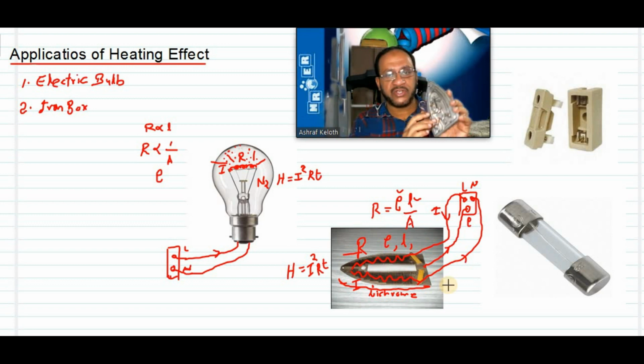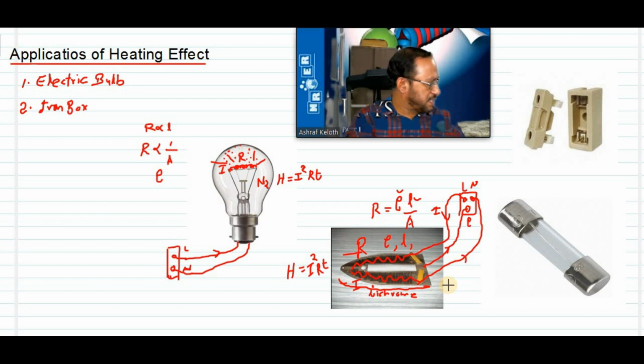In such a situation, you can see there is a screw here, on the metallic body. On that metallic screw we have to connect the green wire of the earth wire. One end of this green wire will be connected here, and the other end will be connected to the thick pin of the 3 pin.